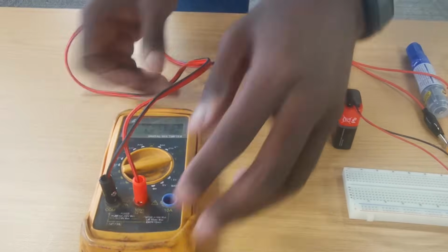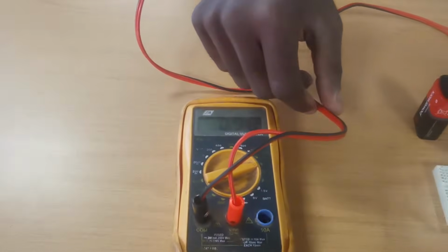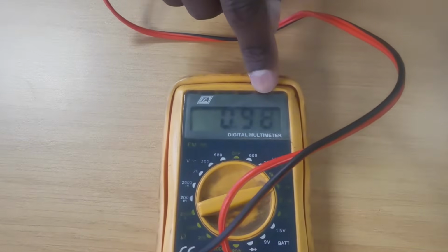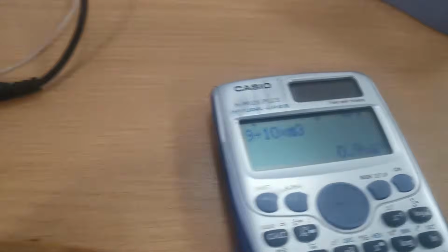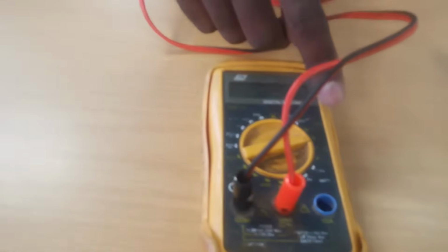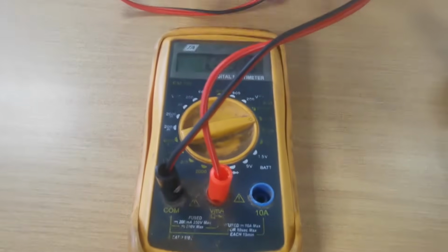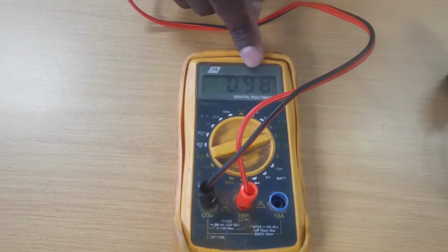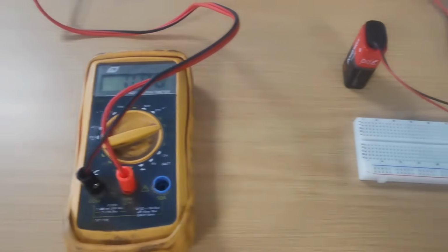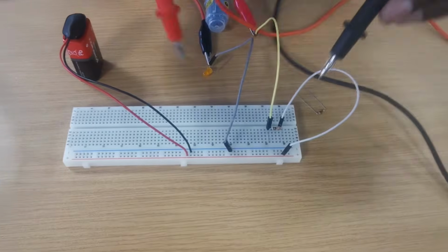Okay, and that gives me a value of 0.98 milliamps. So that was AC current that I was reading there. So you must make sure that your multimeter is on DC current and DC voltage. Okay, so you can see that 0.9 milliamps, and then I can measure the voltage again across the resistor, and